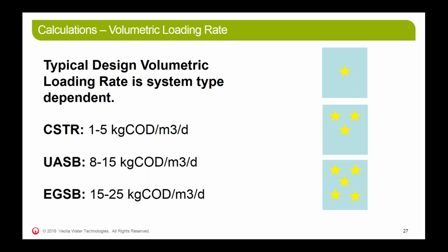So essentially you look at your influent COD concentration and flow and your reactor volume, and that's how the system is originally designed. Or if you have an operating system, what your system should be in the range of in order to operate in a stable manner.